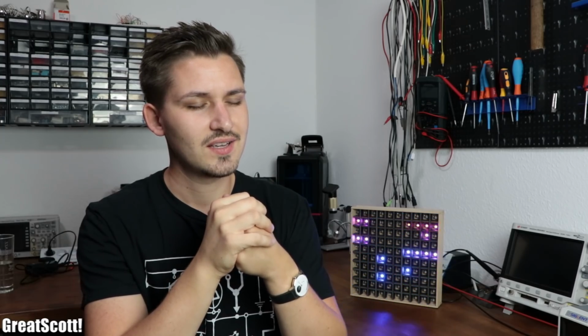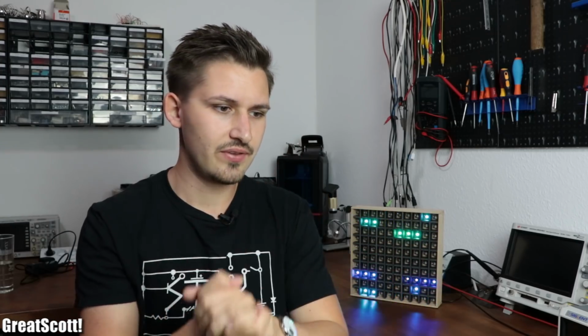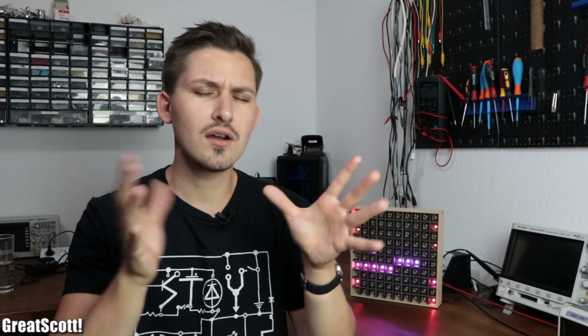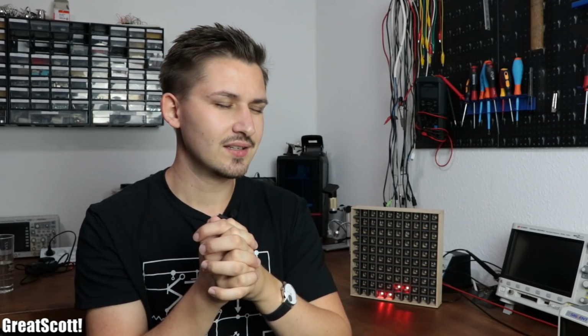And that can now be calculated. You got 7.4 volts, you got 4 amp switching current. So you multiply that, you get a power of 7.4 by 4, by 2 it's 14.8, by 4, 29.6. Let's just say it's 30 watts. So you can put 30 watts on the input. Then you have to calculate with the efficiency. A normal case I would say is like 80% efficiency. So 30 watts minus 20%, that is 24 watts. So you got 24 watts that you can put on the output.